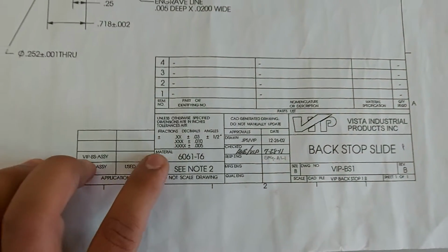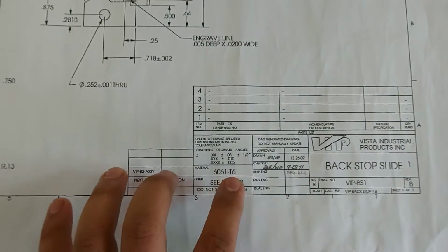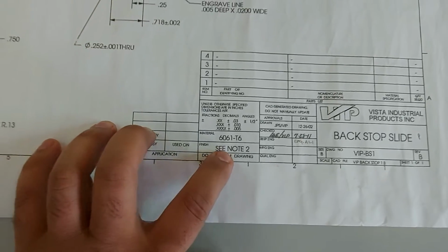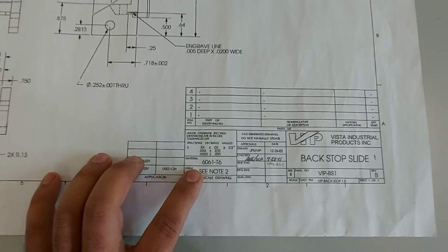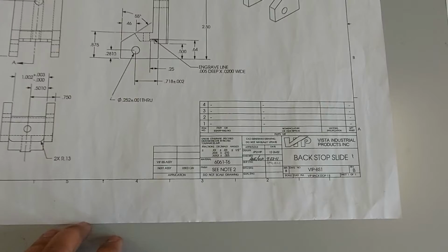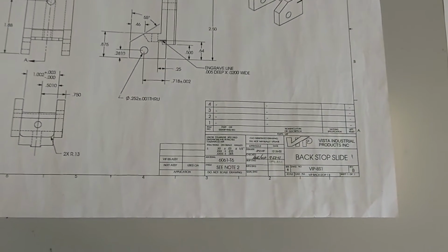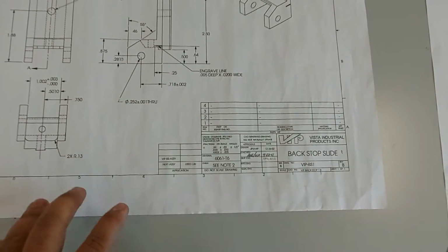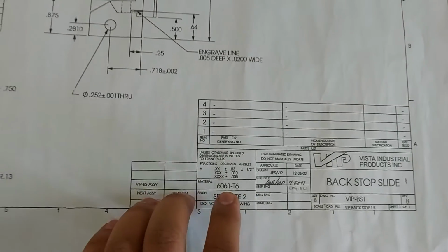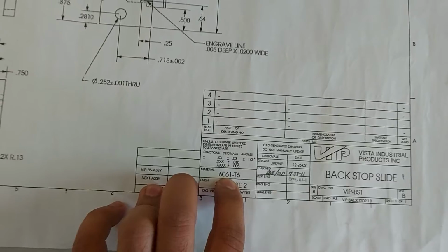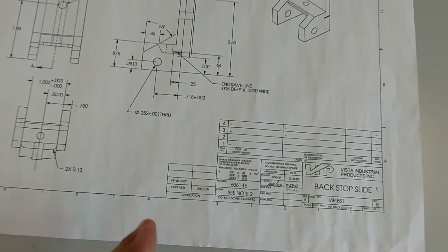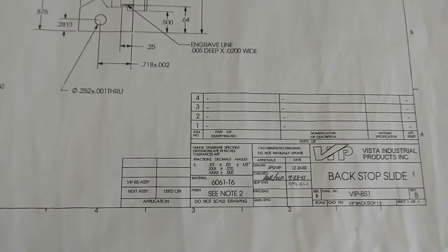Now in the title block you have this material column, where it specifies the material of this part. Here you see a code like 6061 T6. It is an alloy code, aluminum alloy. Basically they don't write each and every composition of the metal. They will use ASME codes or standard codes for the materials or the type of alloys, where these alloys have specific strengths, mechanical properties, and metallurgical structure. So right now they are using this material 6061 T6. If you go to the code book, you can get more details on the material, what the components or composition of the material are.